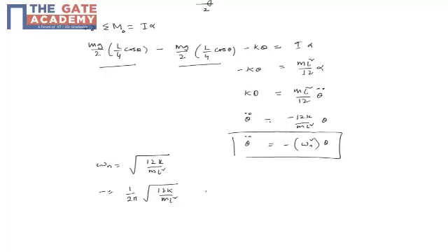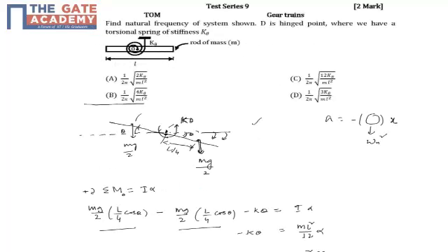The only thing is you have to draw this free body diagram after displacing by angle theta and write it in the angular sense. This is the conventional force method or the moment method. For springs we do the same thing, but we apply sigma F equals ma and then bring the entire thing into this form. So the answer for this is 12k by ml squared.